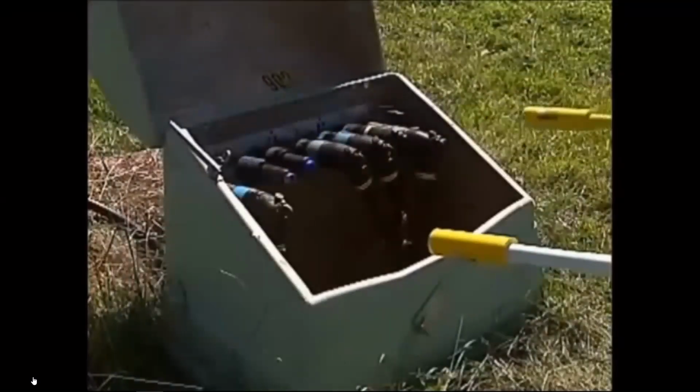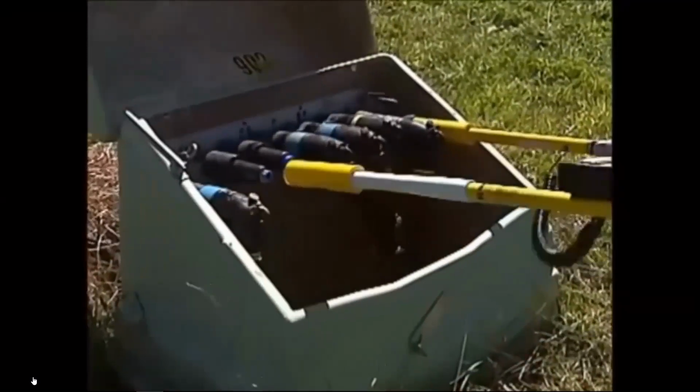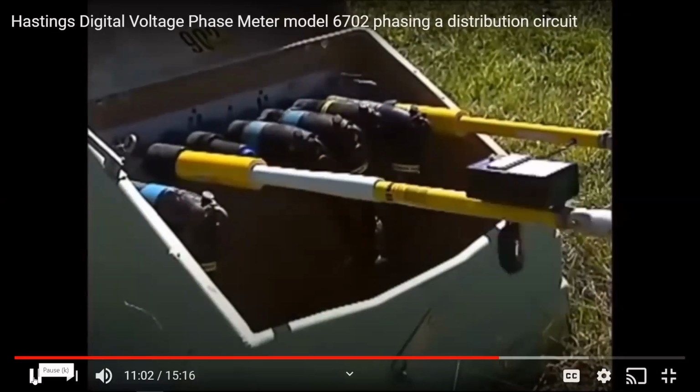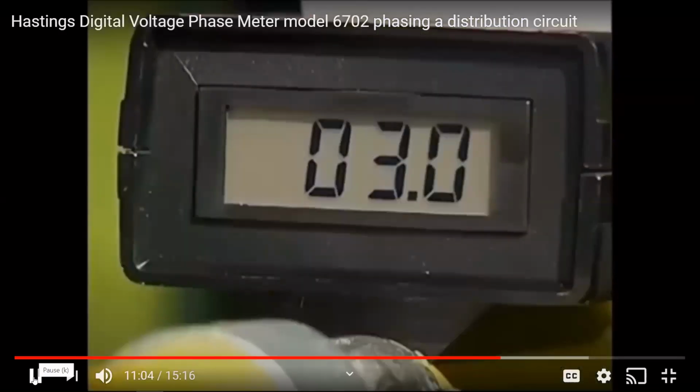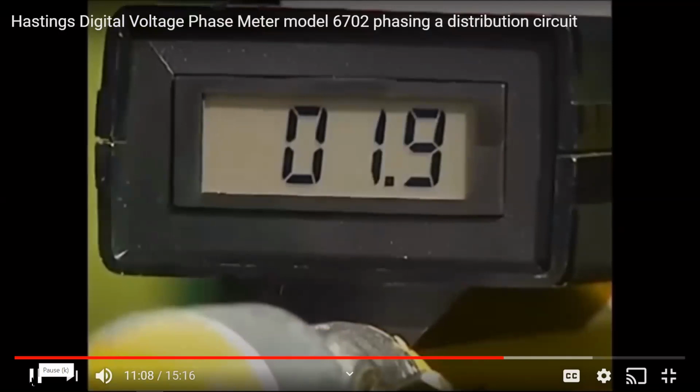Okay, Kirk, let me go into the non-metered end, into the cable to be tested, if you'll energize that DC high pot. Now we got a good initial current flow. It's accepting the charge. It's dropping to a low value.